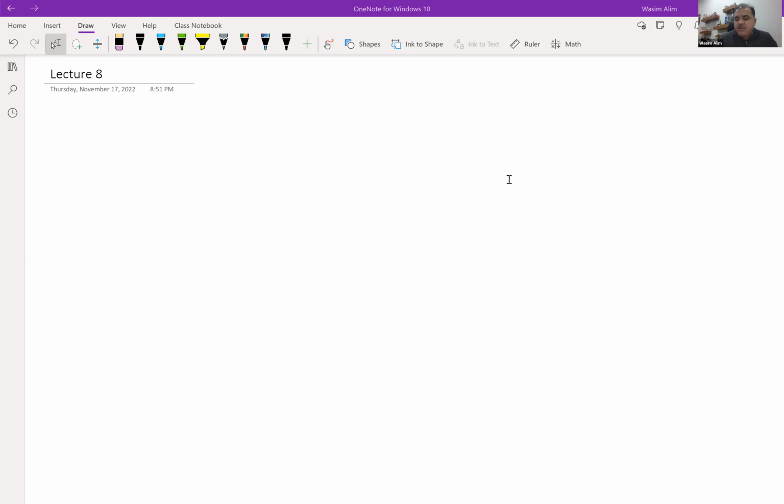So just before we move forward, I just want to give a generalized overview. We talked about how to assign a reference node, how to assign independent nodes, and then be able to draw the currents, the directions, and so on. But one thing that the current source does for us is that we don't have to write it in terms of the voltages, because that's typically a constant value.